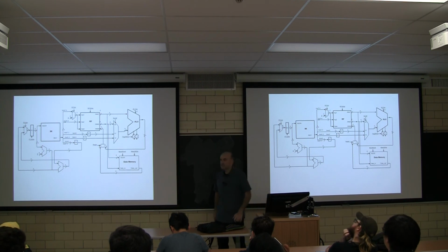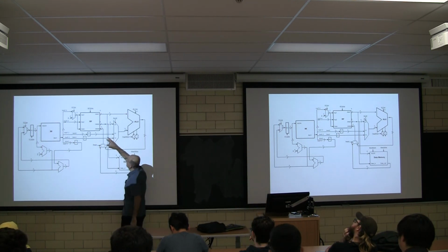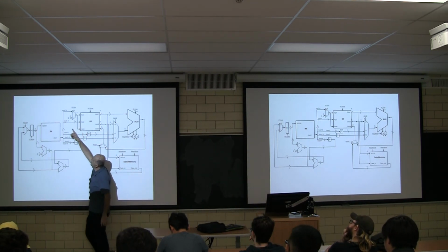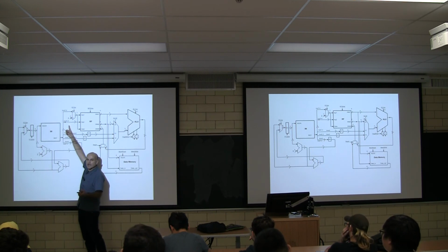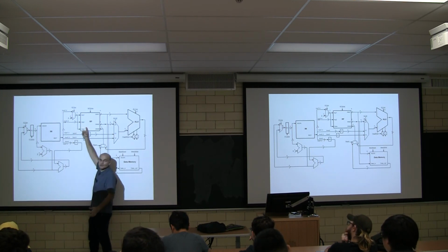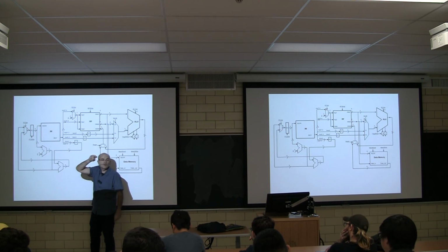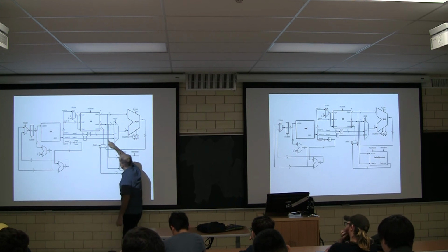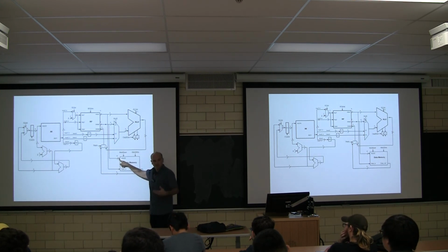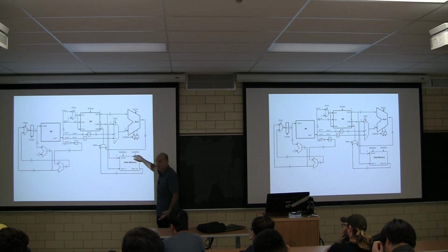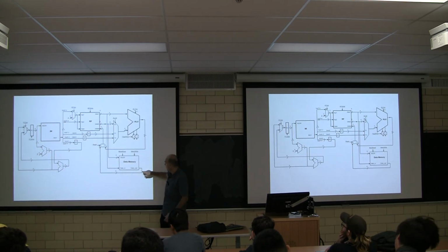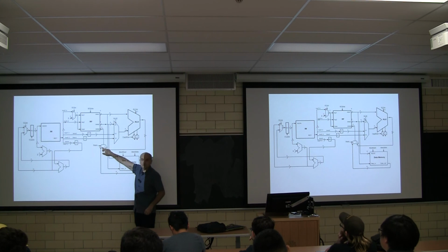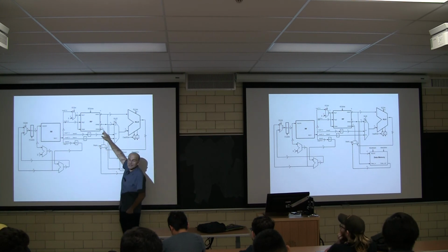As you can see, there is a way to send bits 5 and 4 from the opcode to the register file, so we can use R2 from the opcode to read a value. That can travel as an address to memory. We can read a value from there using that as an address. That value, however, only flows as a potential input to the write port.